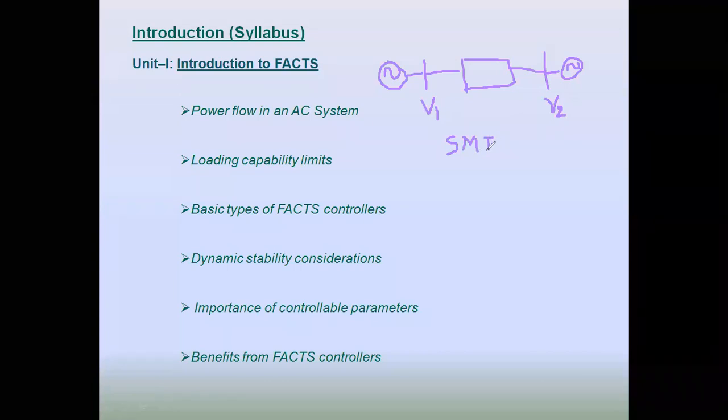This is the simple power system where you can analyze the stability and everything. That is the infinite bus bar, meaning the voltage is almost constant irrespective of the generators or loads added to it. So that is the single machine connected to the infinite bus bar. If you consider load at the receiving end, or one more generator, with different loads, you will have loads at the different buses also. Don't think that only 2 generators are connected. So you will have a load here at this point. You can consider it a 2-machine theory.